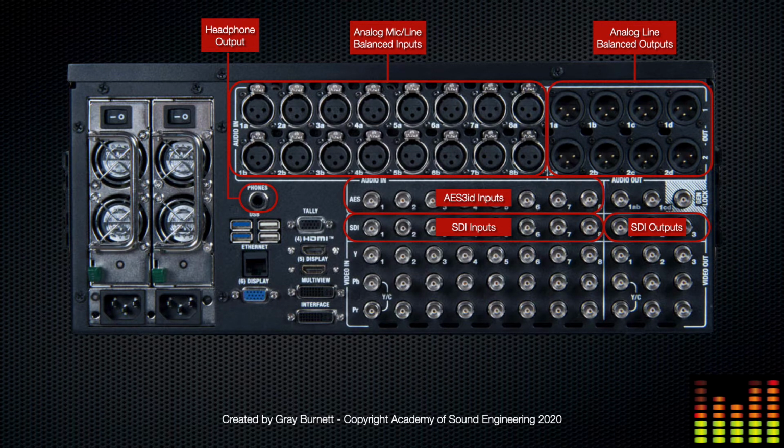We've got our 8 stereo AES3 inputs and 2 stereo AES3 outputs. These are permanently connected to the Lawo core as sources and destinations, and are preferred over the analog inputs and outputs as they are not susceptible to level mismatches and any possibility of noise being induced.